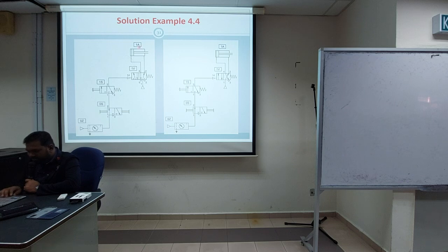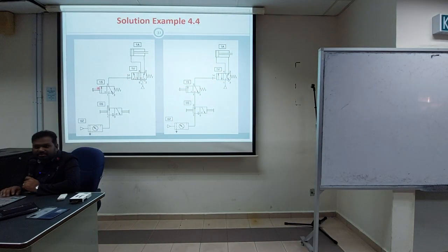Okay, so you can look here. The indirect method, so what is the name of this valve? How many ports does it have? There are 3, 1, 2, 3. How many boxes? 2. So 3/2. Okay, so 3/2, push button operated, spring return.